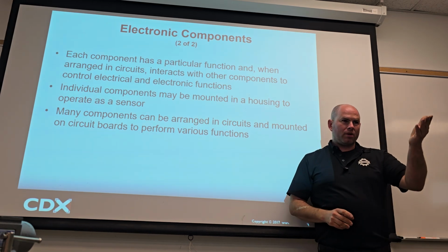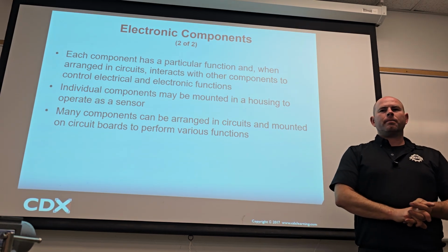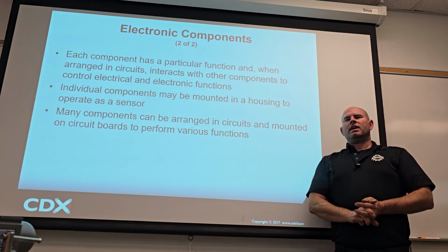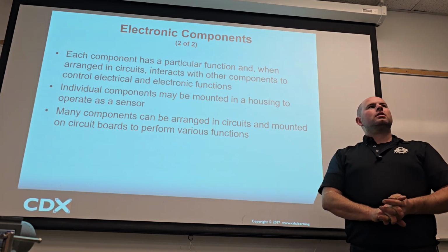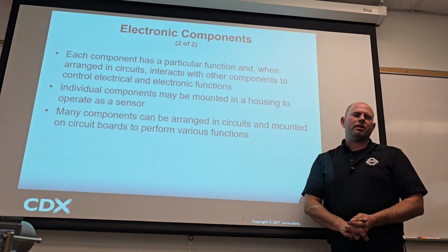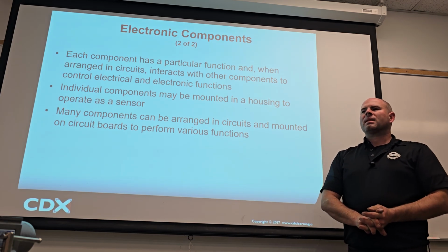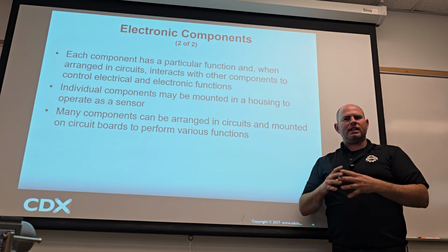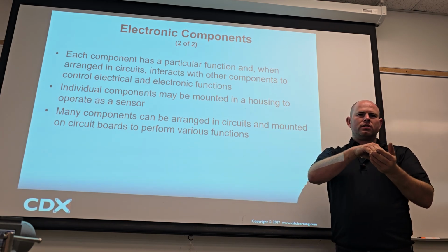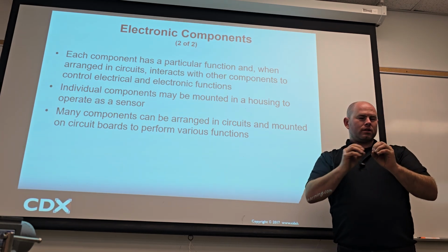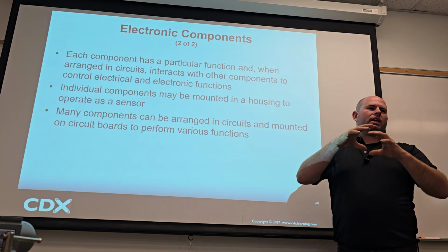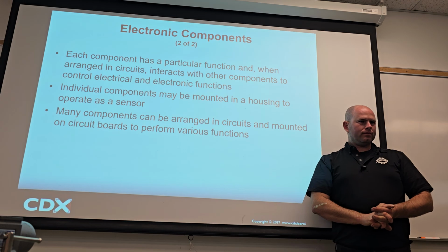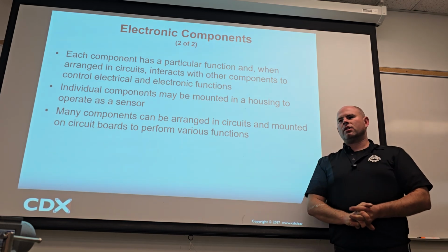So another example, that heated O2 sensor problem. The problem with that sensor was heated oxygen sensor, heater circuit open, more or less. The way that sensor works, it needs to get 12 volts to run the heater so that the sensor will get hot. If your sensor is cold, did you know it doesn't work? With heated O2 sensors, they don't work till they're hot.